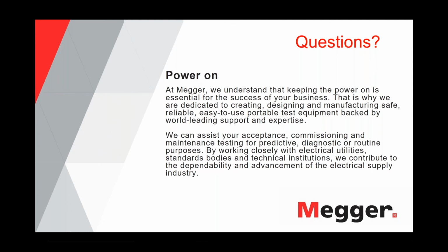Also, that depends. On the tan delta, same thing. It depends on the results. If you have a cable that is already service aged, but it has very good results, and it might not be an important cable, you test less frequently than if it is an important cable. And the same goes for the PD testing. So it really depends. And maybe Henning has something to add to this, but if the condition gets worse and worse and worse, you would test more often.